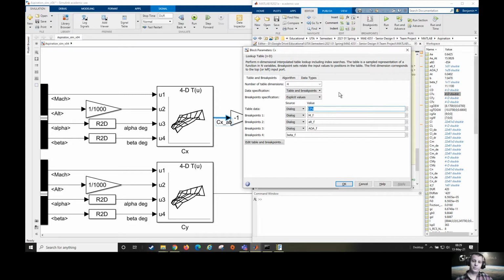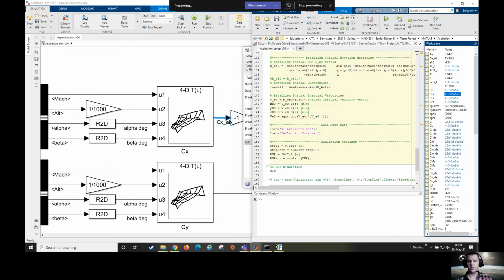And you would just take all that data and export it out of VSP Aero, bring it into MATLAB over here, and you would need to build a 4D, 5D, 3D, whatever size array you want for whatever you're doing. And that's how you can build these multi-dimensional arrays. And there's enough YouTube videos showing VSP Aero and building multi-dimensional arrays in MATLAB. But that's how, brief walkthrough, you could do it.